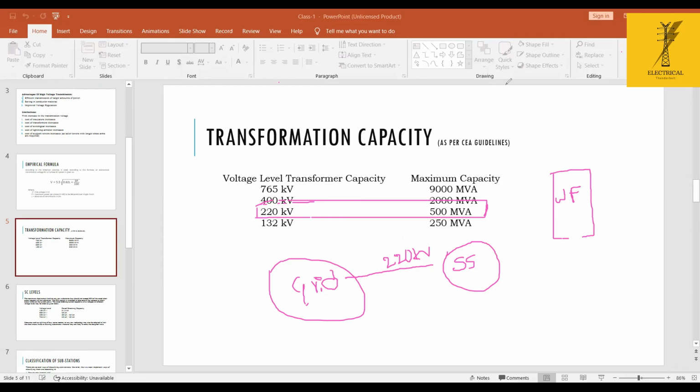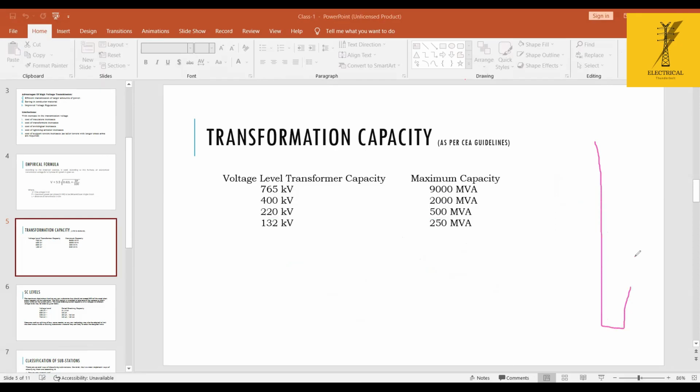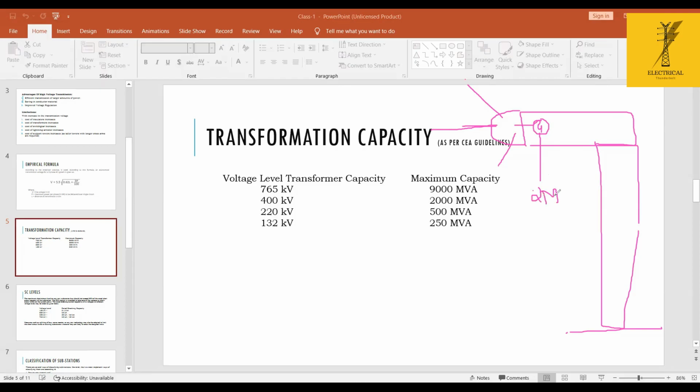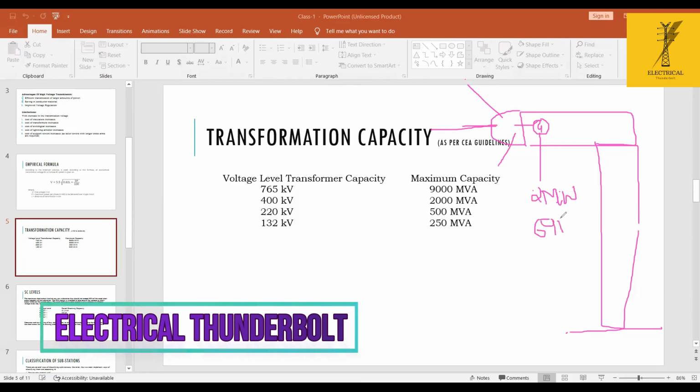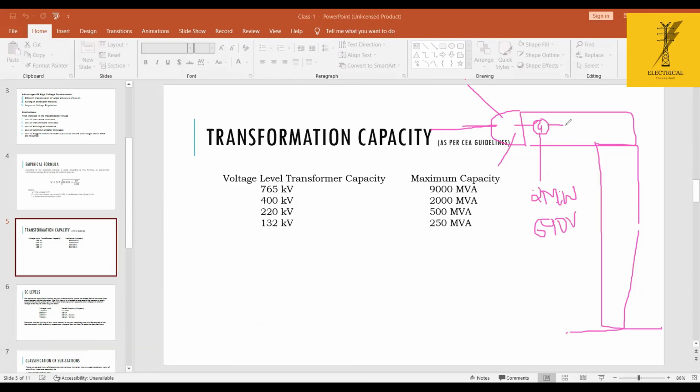See, I'm just giving you an idea of the wind farm. This is the wind turbine, and we have a top one, and this is the hub, and these are the fan blades, this is how it looks. This is the tower, this is the hub, these are the fan blades which rotate, and this shaft is connected to a generator. This generator is generating 2 megawatt of power. Each wind turbine will generate 2 megawatt of power at 690 volts. So this 690 volts is stepped up to 33 kV at the top.